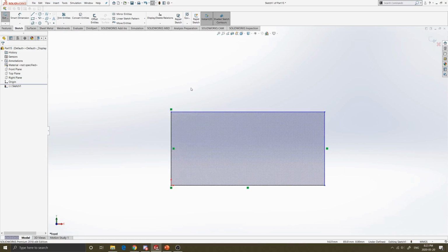These properties and relations for lines help define how your drawing is to be made in 3D space. As you can see, there are these black lines here, and these blue lines right here. That typically means that these lines are fully defined in this 3D model. These two lines are based on this origin point right here, and this line, for example, has a relation of going in the vertical direction. That means the line has to start at this point and it has to go up.